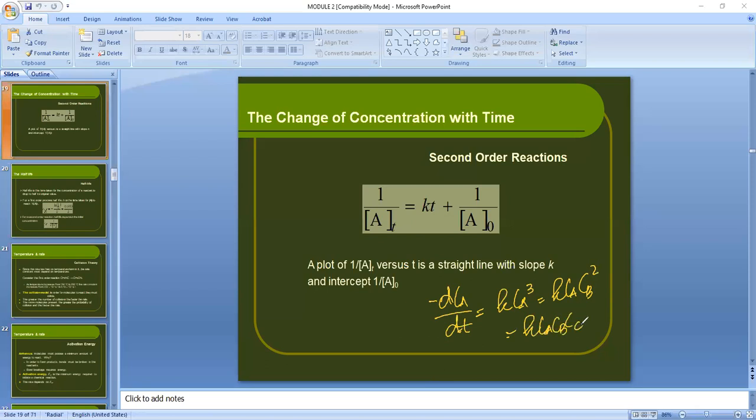Right? So it's very important that when you have the rate here in terms of A, all your concentrations here will be in terms of A. So you need to express CB and CC in terms of CA. Going back again to that fundamental relationship I gave you, that CAO XA over a is equal to CBO XB over b, and so on and so forth.